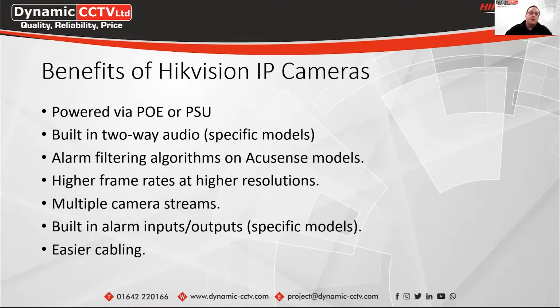So what are the benefits when it comes to Hikvision IP cameras? Across the range, generally they're powered via PoE, which you'd use either the PoE ports on the back of the recorders or individually using switches, depending on the size of the system or what's needed for the site. It would depend on whether you go for PoE switches sat across the network that are then routed back to the NVR itself, or whether you can plug them directly into the back of the recorder itself.